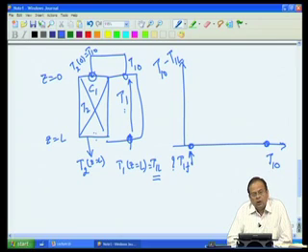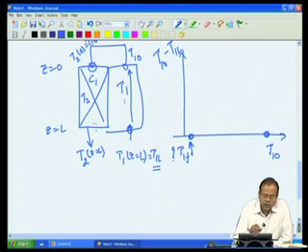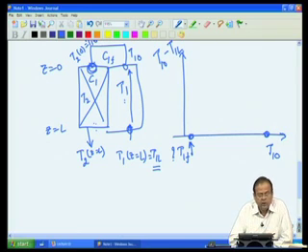Let us consider the other extreme where T10 value is so high and is of a specific value such that this T10 corresponds to the temperature at which equilibrium is achieved vis-a-vis the inlet composition. So, corresponding to C1F, if T10 value is such that the equilibrium is already achieved at the inlet point, no reaction can take place from inlet to exit.